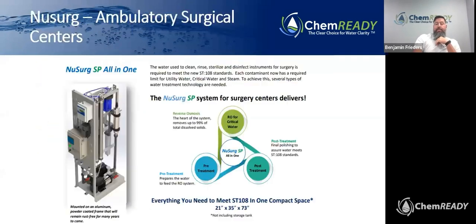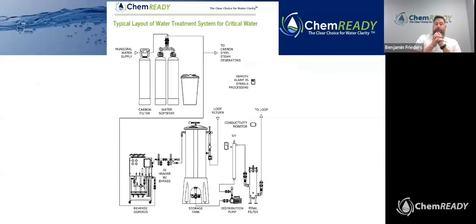Per the standard, what that means is if you come to a critical water system, it means that after each treatment step, carbon filter, water softener, reverse osmosis, DI, UV, and bacteria endotoxin testing, you require intensive daily testing against table 2, all of those ionic contaminants I showed you before, for a period of time, and then at a reduced frequency for a year.